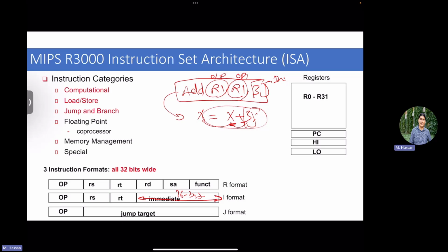Like you need to take the low first, which is basically 16 bits, put it in one register, maybe the low of the register, then take the second 16 bits, put this in the high of the register, and then use the registers to add, for example, right? We're going to discuss this later on, but just to have a sense of how ISA definition limits your implementation, limits the capabilities the machine can have, right? This is because it's a contract.